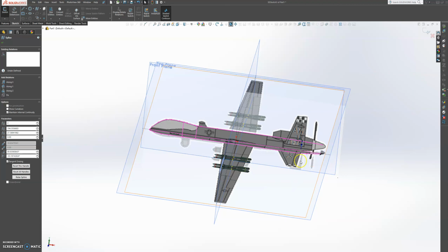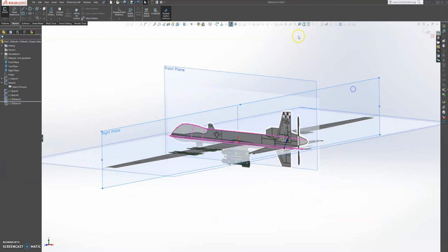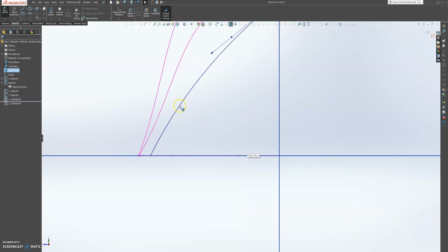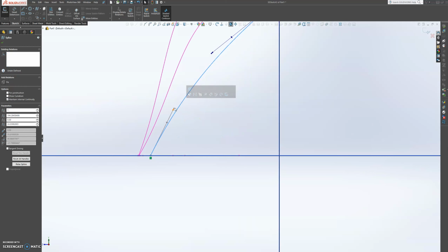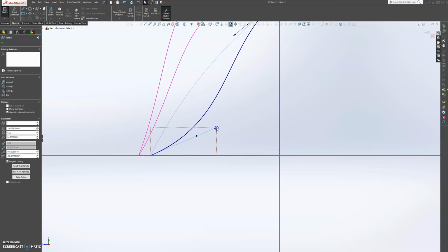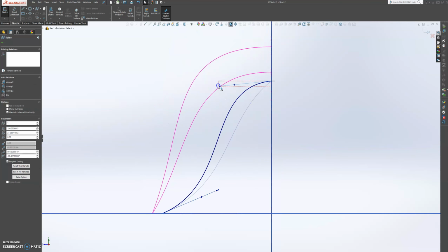Okay, so knowing that, let's go back to this normal to profile view, and then we're going to click on the spline, and we're going to introduce quite a bit of flare on this back end. Bring this up here just to make things nice and smooth. Click on that control bar and then fix it all along the z-axis.